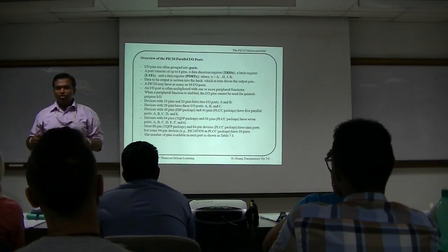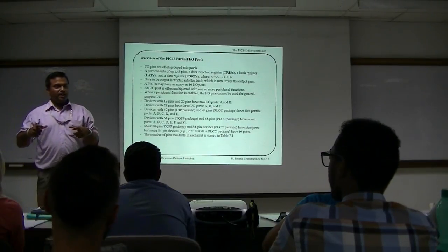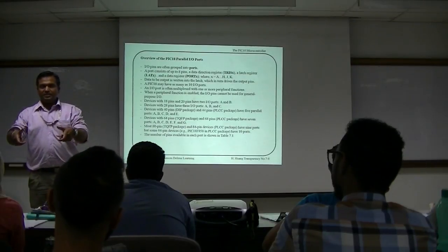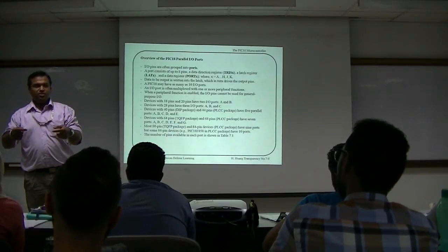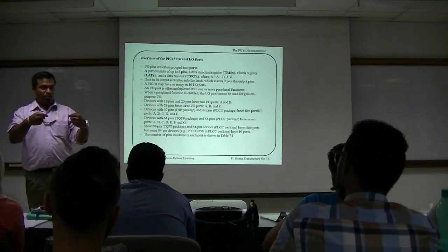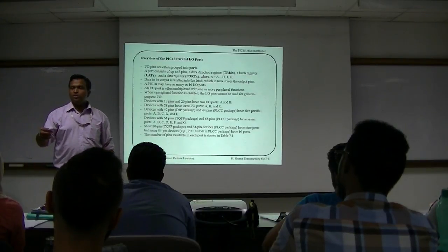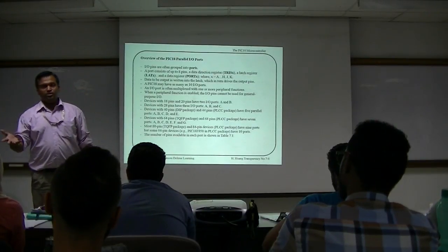So from the data port, you only write to the data port. From the data port, it actually will transfer to the latch register. The latch register is actually connected to the pins, the hardware pins, circuitry, and which will provide the correct logic to that particular pin.